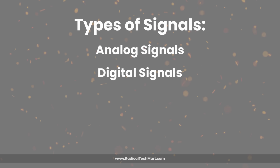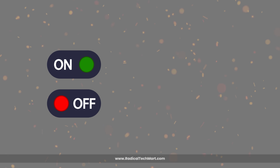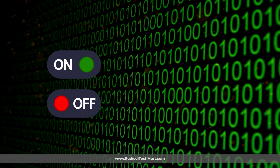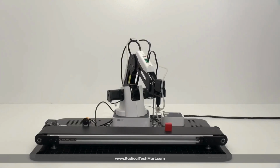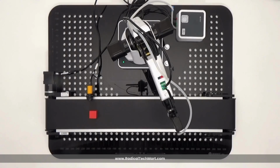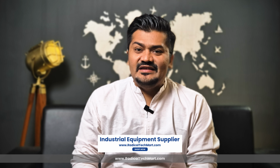Next, we have digital signals used in modern automation systems, mainly giving output in either on or off, represented as ones or zeros. This makes them highly reliable and less affected by noise. A simple example is a proximity sensor in a conveyor system. It detects objects and sends high or low signals to a controller. Digital signals are great for fast and accurate decision making. Second example you can take is push buttons in control panels.